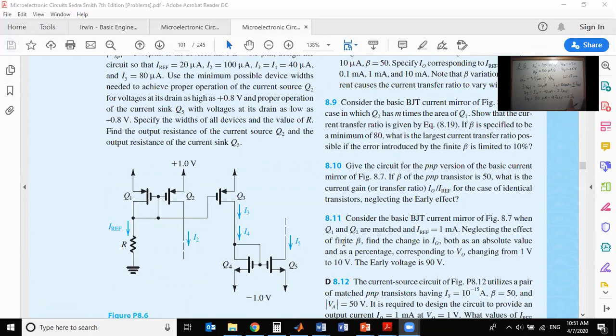You're right. So we're gonna use this, not this one. So are you going to just find the ratio between the currents and the reference current, and then use W? Yes. Basically, this is a repetition of W over L ratios. We're gonna repeat, but we need to know because actually we don't have W's here, right?